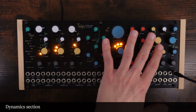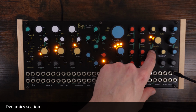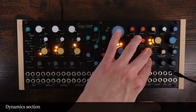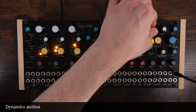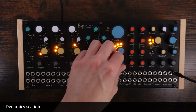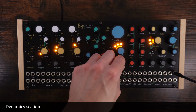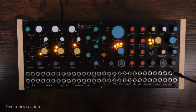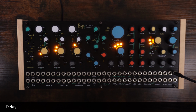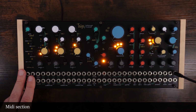The filter is then directly connected to the dynamics module. The dynamics section has 3 different modes. It can act as a plain VCA, as a low-pass gate controlled by the ADSR, or a plugged low-pass gate with adjustable response time. The 2 ADSR envelopes are normalized to control the dynamics section and the filter respectively. And you can dial in the amount using the FREQ CV2 and the DYN CV attenuverters. At the end of the signal chain, we have a bucket brigade delay, which can have delay times of 16 to 250 milliseconds. The brain of the module is right here, the MIDI center.